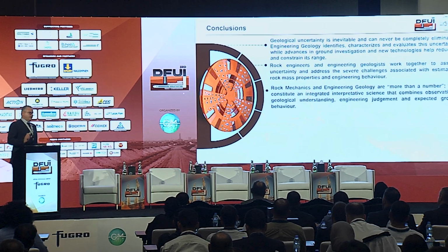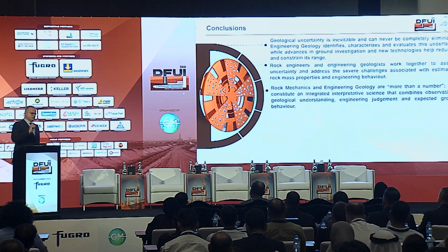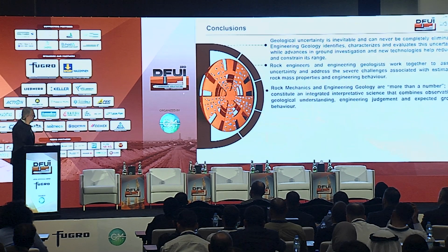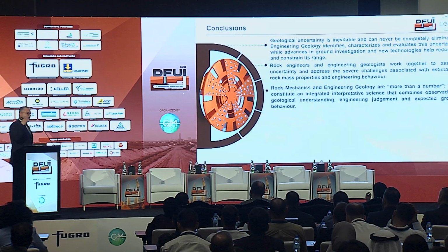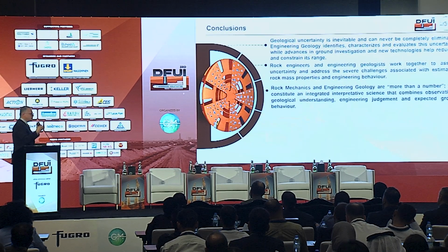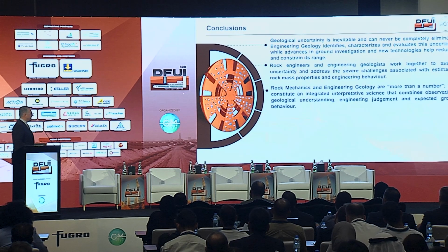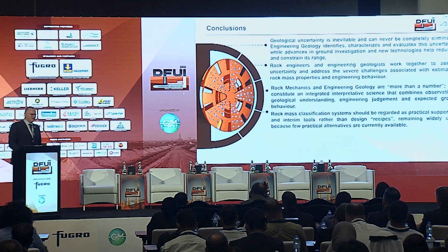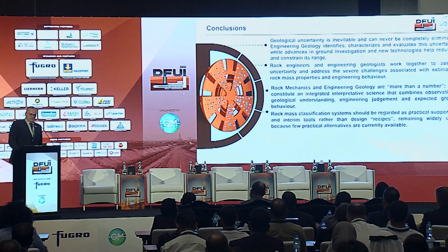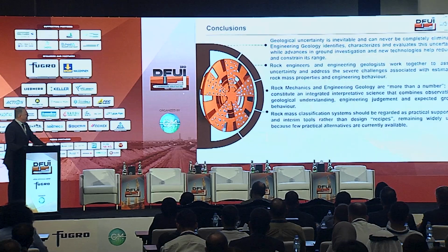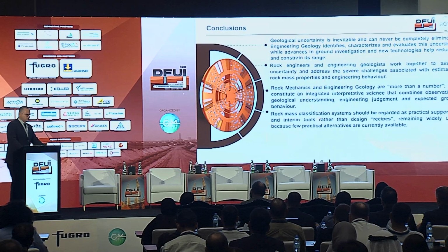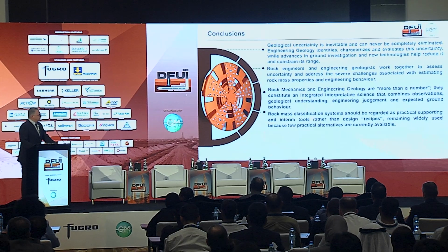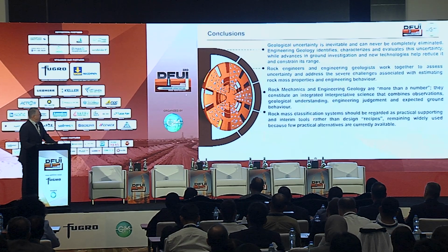And we need to understand that this synergy is not just about one number. They constitute an integrated interpretive science, combining observations, geological understanding, engineering judgment, and expected ground behavior. So rock mass classification systems should not be regarded as design recipes. Mainly, they are practical supporting and interim solutions. They're really valuable to our tunnel practices, so we need to use them accordingly.